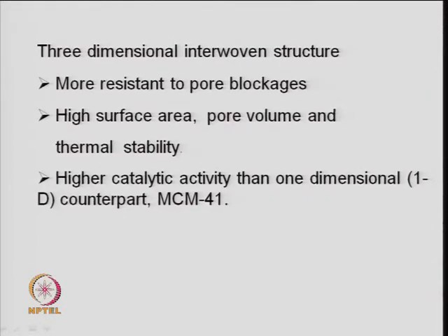They have high surface area, high pore volume, and they have good thermal stability, because stability of zeolite is one of the important issues, right. At high temperature they do not sustain their structure, it collapses, right, when you have high temperature, because the framework collapses at higher temperature, right. And higher catalytic activity than 1D, which is your MCM 41. So, MCM 48, which is a 3D type structure, has certain properties in terms of the catalytic reaction.